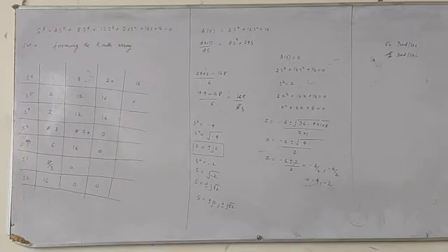So when this type of question arises, and you are not able to ascertain whether the system is stable or not, then you have to check the roots. Once you check the roots, if you get pure imaginary roots, that itself indicates the system is marginally stable.